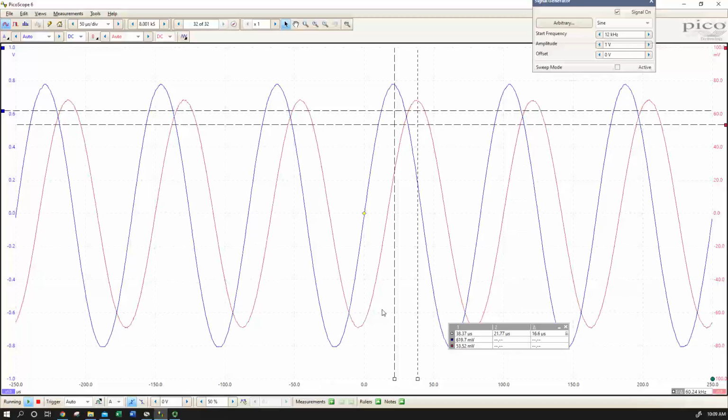And we just demonstrated this by creeping up on our resonance frequency, incrementally changing our applied frequency to the circuit and seeing how big the changes were in the relative voltage drops over our series resistor versus the total circuit.